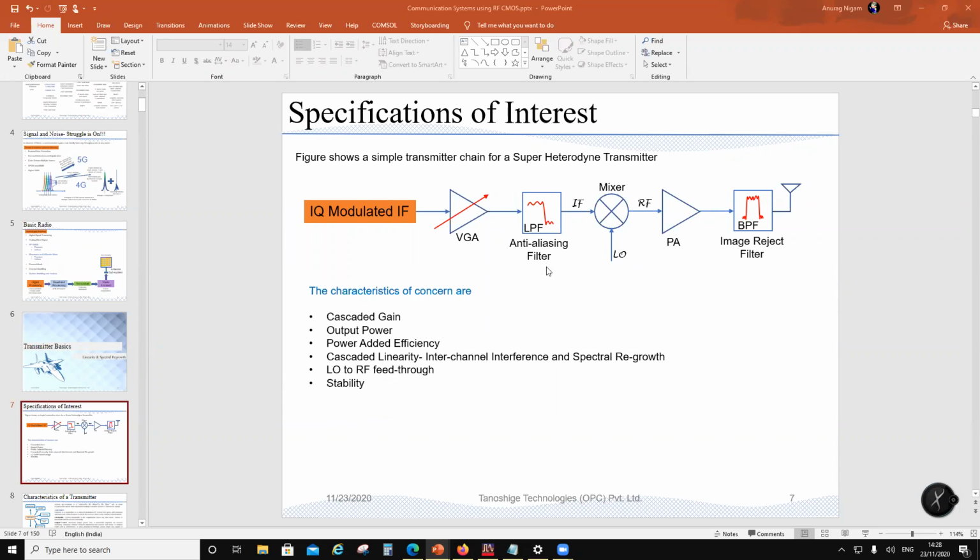Of course, then there are different forms of transceivers. Basically you can have a direct conversion, or you can have a low IF, or you can have a superheterodyne, where there is an IF, or you can have a dual conversion with two IFs. It all has to do with how efficiently you can filter. That's why you go from RF to IF: your filters can have sharper edges. So a lot of things have to do with it.